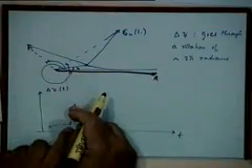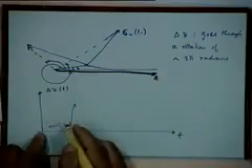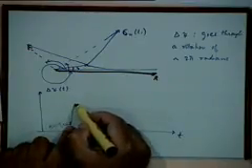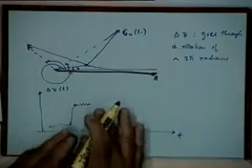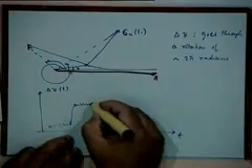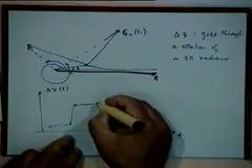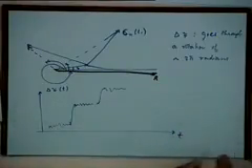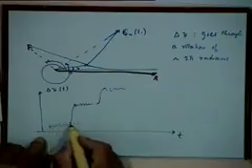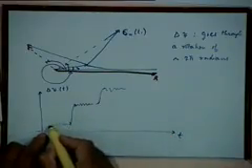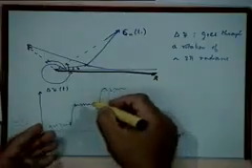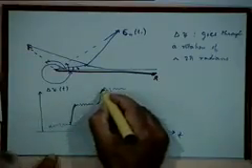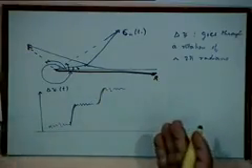So the output of the phase demodulator will show up like this. You are getting some constant value of psi with some fluctuations, and suddenly there is a jump. Then as long as you are here, it will be like this, right? And once again, after some time, whenever the second spike occurs, there is another jump. So this will be the behavior of the output of the phase demodulator now. Instead of remaining at the constant value of psi with noise all the time, you will go through these jumps, right? The time interval of this duration is going to be of the order of 1 by w.